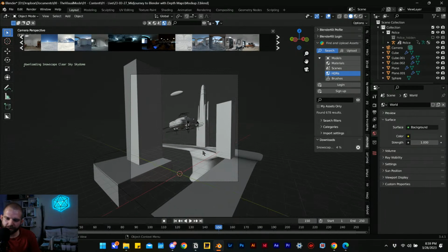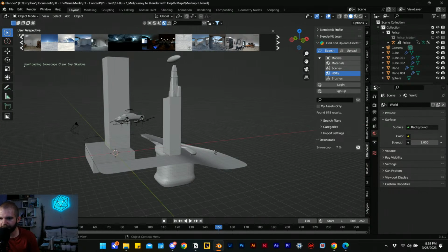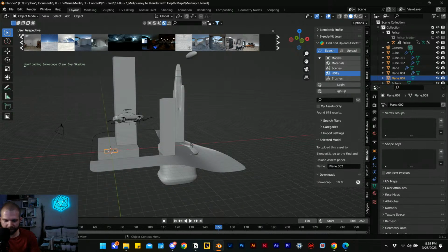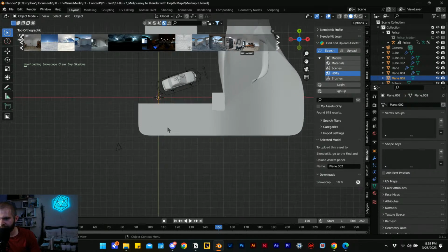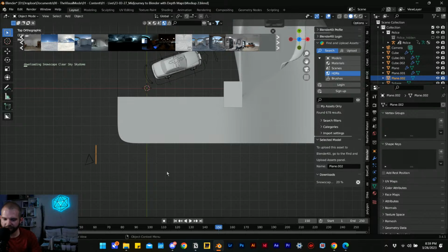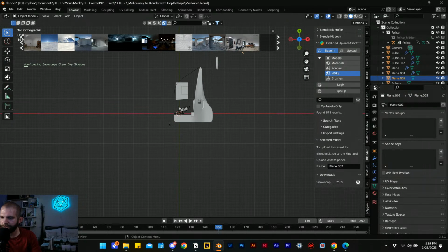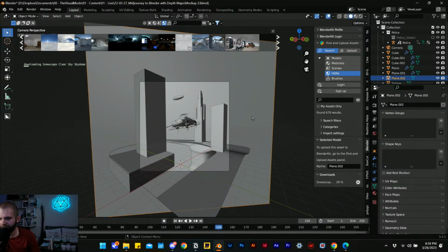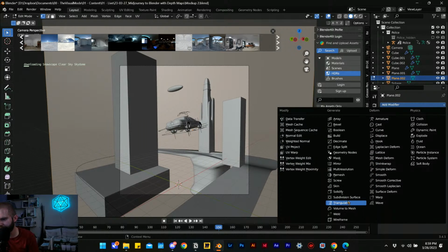And I do recommend, just to have that lighting match, put in a plane in the background lined up to the camera. I'm gonna do it roughly right now, rotating it this way, and then kind of matching the angle that the camera has here, so that this face can have the background projected onto it.